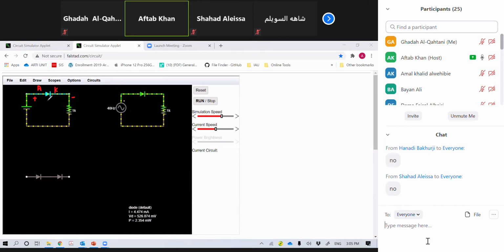All right. Now we can also see, rather than this DC, what happens if we connect the AC. See, here is AC, and what is the property of AC? AC goes to maximum, then it comes down, right? We know this one. And again it increases, again decreases. So what happens? When it reaches above 0.7, the diode will conduct, that is, the diode will be on. And when the voltage comes below 0.7 or 0, the diode will be off. At that time it is off.